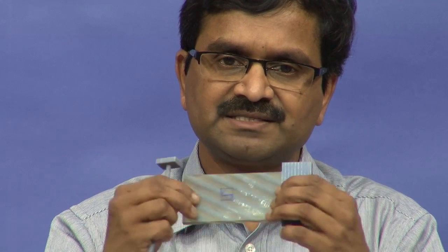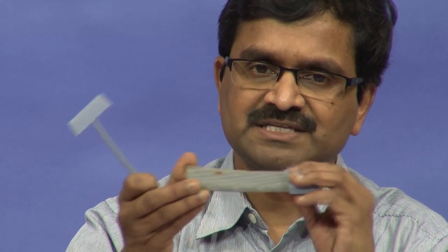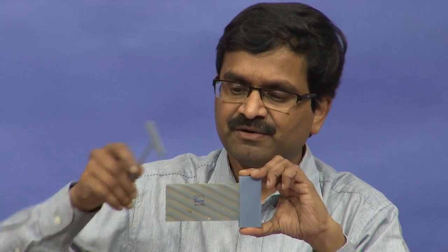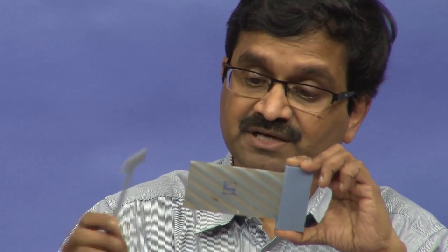So, it actually is twisting in addition to bending, and that is happening because of the anisotropy that exists in this one. That is, its stiffness in the bending and twisting directions are adjusted. Basically what you have is a slab, of course it is 3D printed, but imagine that you have made a material where that slab itself has anisotropic properties. In this particular case, the blue ones you see are rods, all stiff material embedded into a flexible material, which is the translucent material here. So, because of that it is getting twisted.